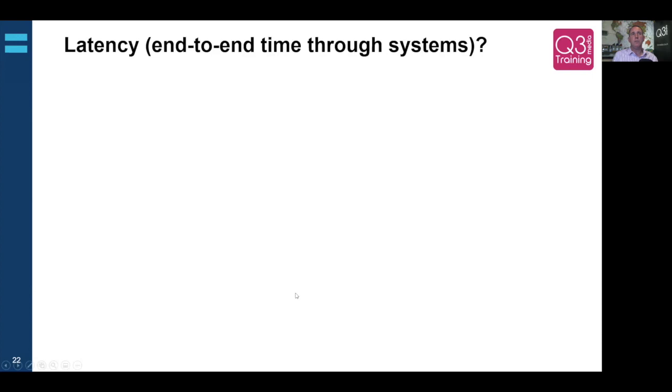So some of the things that it's worth comparing when looking at SDI versus IP. Latency. This is the time it takes signals to propagate through a system, and how that affects things. In broadcast, we've always tried to think of broadcast as a real-time process. In the days of analog, it truly was. With the advent of SDI, arguably there's some buffering that goes in there, but the latency is generally very negligible because it's a matter of lines of video rather than frames of video.